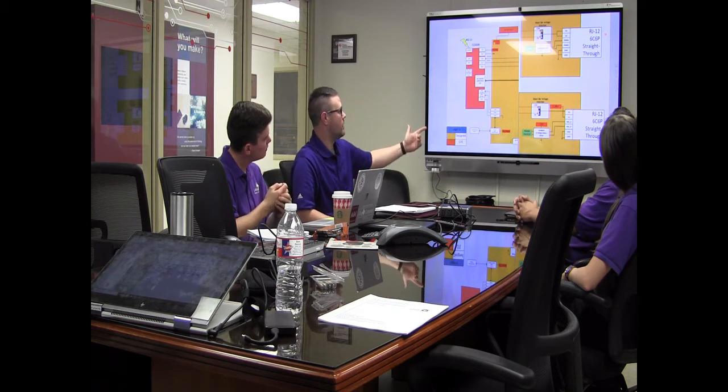And then on the H bridge, the next 4 ports, you have the selectable voltage again, as well as a 12 volt sourced DRV8870 H bridge motor driver that you can use. It's an H bridge, so you can use it either way to turn a motor back and forth, or in our case, we're using it for dimmable LEDs to turn on or off higher current loads. And actually, the PWMs are on the bottom side, right? I think the grounds and the PWM should be switched, actually. You're right. Yeah. So I guess we can change that, we'll update that.